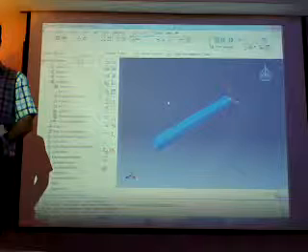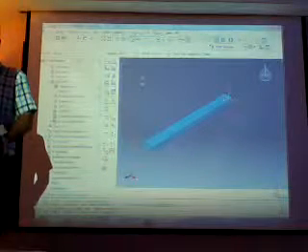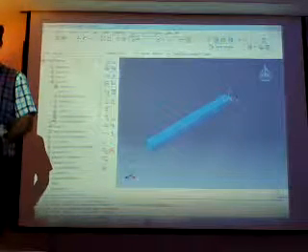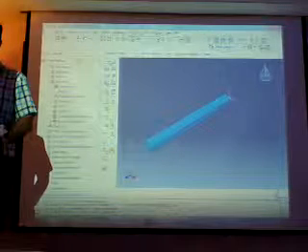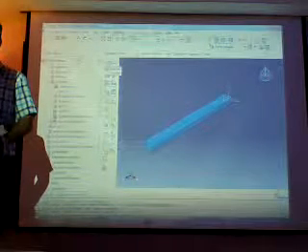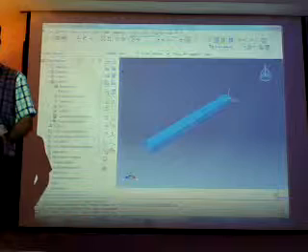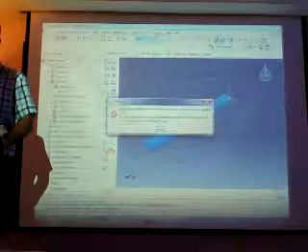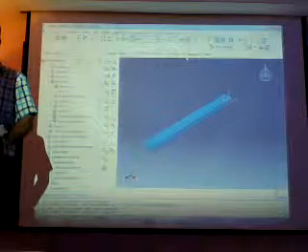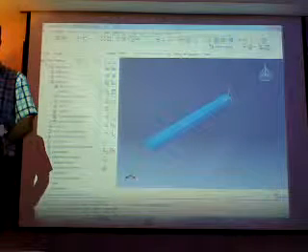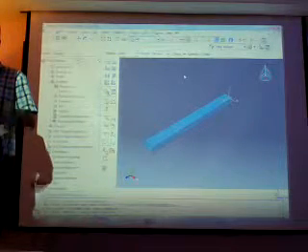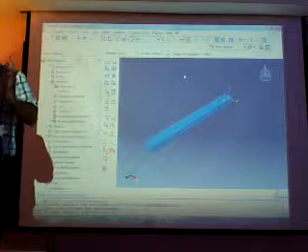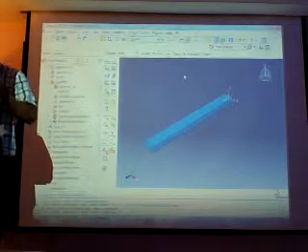After that we have a mesh part. In the meshing first you need to define your global size or seed mesh size. In first icon, as you can see here we have two different kind of object, assembly and part. If you remember, in assembly I take a dependent mesh on part.